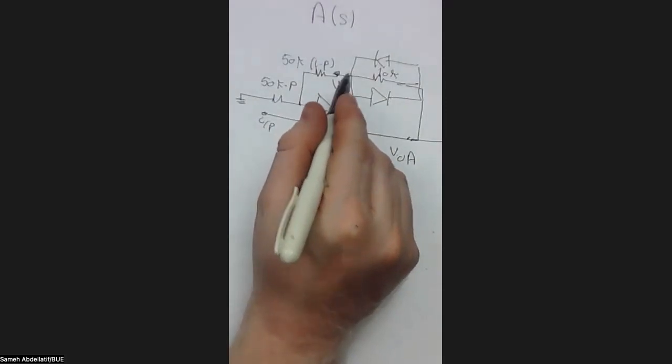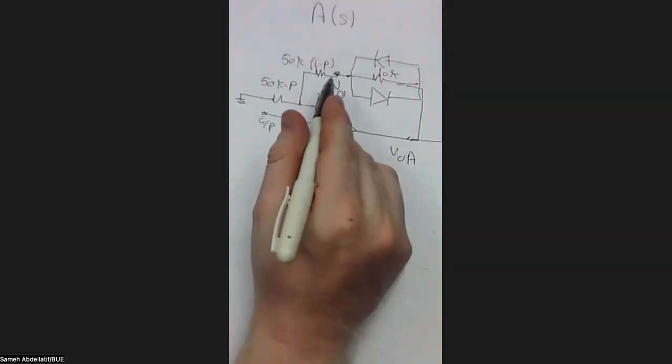When you determine this A of S, your concern should be the relation between input and output of the amplifier. So you are not going to include this, or it's not your task now to discuss this point. But you have to consider the relation between these 2 points, because these are the points constructing the amplifier. So let's see how this circuit is going to control, or limit, the input, because actually this is the task of this network, to control the input.